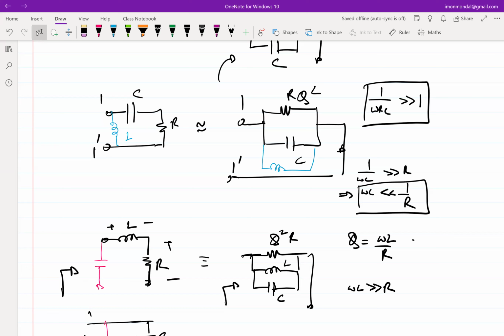So in principle, how is this impedance transformation happening? You are trying to store more and more energy, either in terms of voltage or current, into the matching network. Higher the Q, more the amount of energy that you are storing. Which means you can think of it like more amplitude of current and voltages in the inductors and capacitors, right? Now, if the inductors and capacitors also come with some lossy element, that increased amplitude of current is going to have increased amount of loss, right?